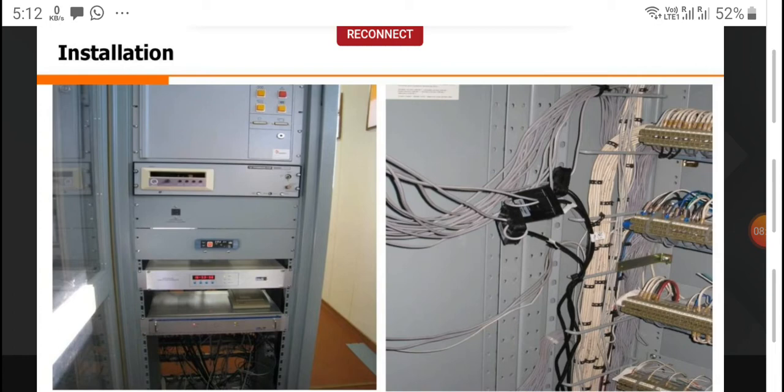So, you have got these secondary CTs, as you are seeing over here, the black CTs that are hanging with the wires. These grayish wires are actually your CT wires, and they are coming from the field. These are primary CT inputs, and these are your system inputs. That is, these clip-on CTs will take input to the data acquisition unit, at both ends of the substation. So this setup will be there at one substation, and a similar setup will be there at the other end of the line, at that substation. So this is what the system is all about.